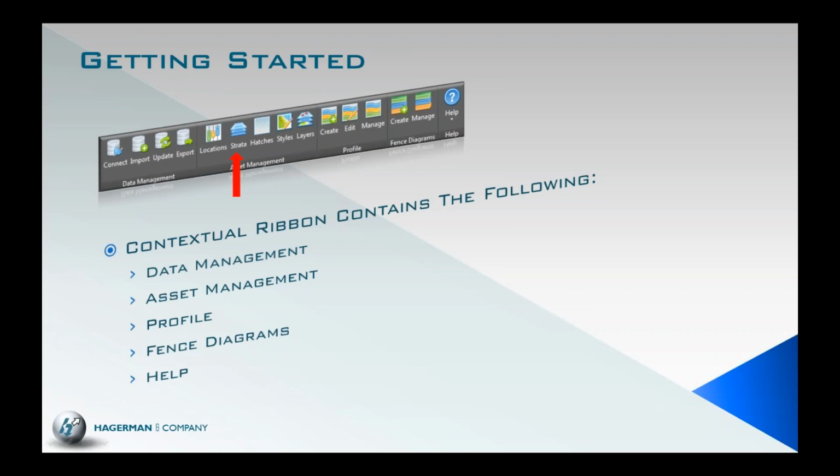Now, the surfaces that are created are standard Civil 3D surfaces. Anything that we can do to a surface that we've created, say existing information, we can do the same here. We can change how it looks. We can change the styles. We can change vertical exaggerations. So it's not something that's going to be completely foreign to us.